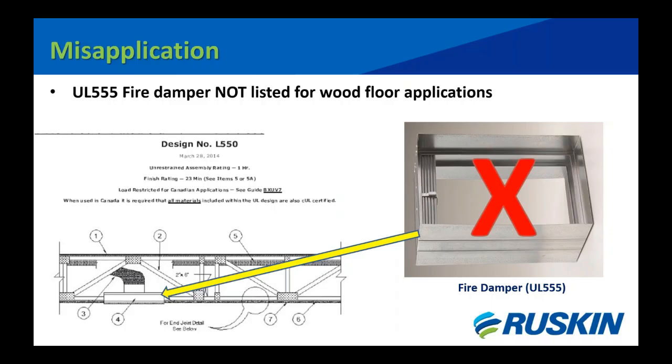So this is something we're trying to help people not get into. So UL 555 fire dampers are not listed. The code talks about, install per the damper's listing. So this would not be listed for the wood floor installation.